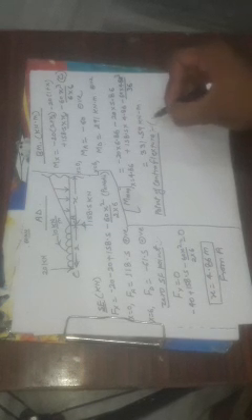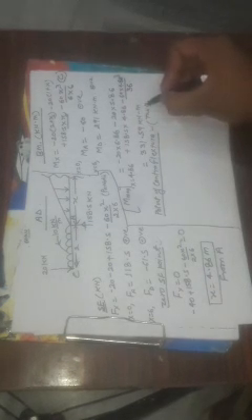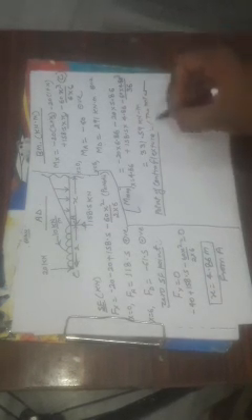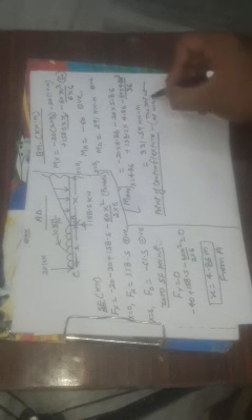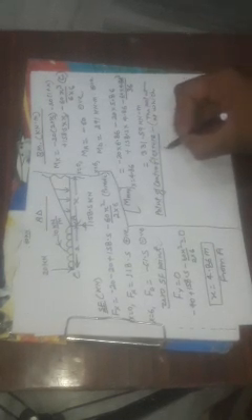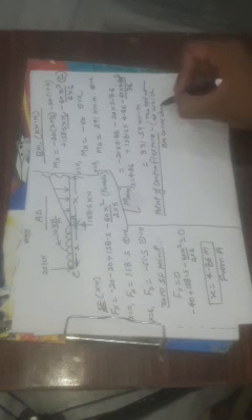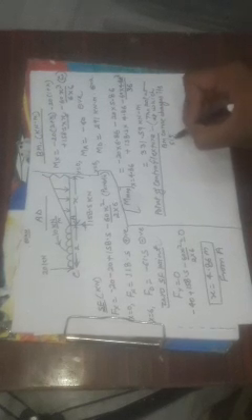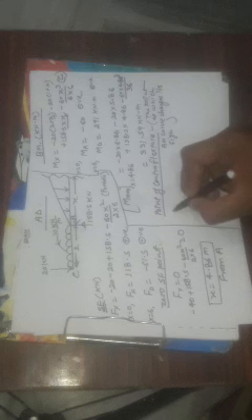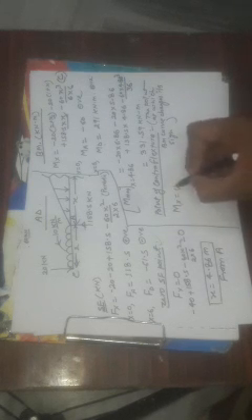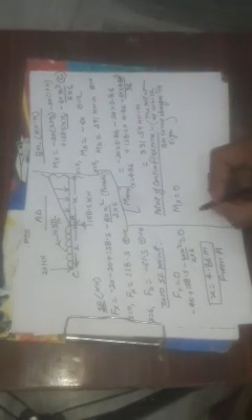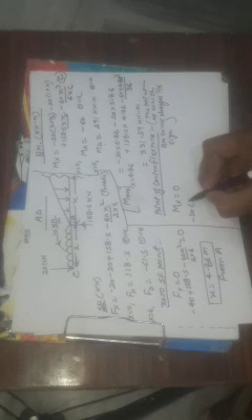What is point of contraflexure? This is the point at which the BM curve changes its sign. Right? So the bending moment Mx will be 0 here. Make this equation equal to 0.